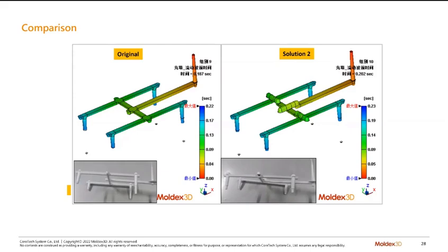Here's the next one: how to reduce the stress mark in the molding process without changing the product design. In our case study 1, it doesn't change the product design. You only change the cooling channel, the mold design, to provide a uniform temperature distribution in the cavities and reduce the residual stress. And furthermore, it fixed the stress mark in case 1.